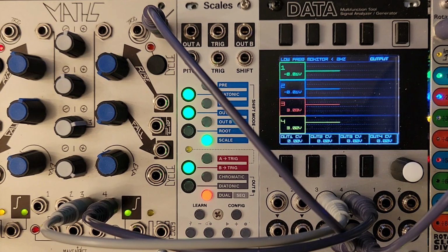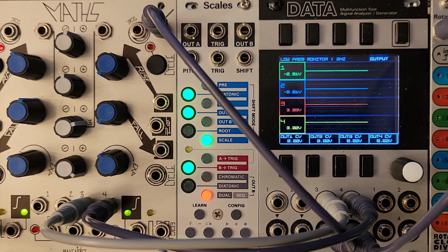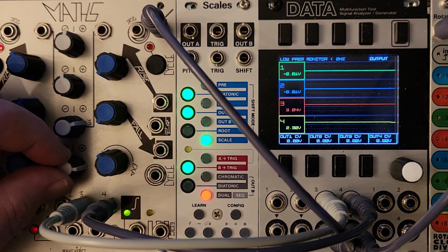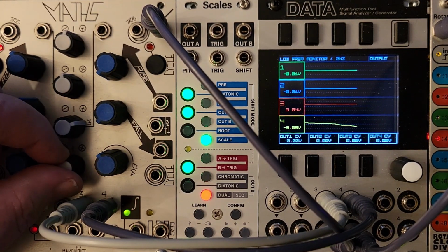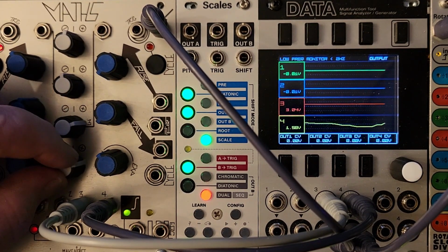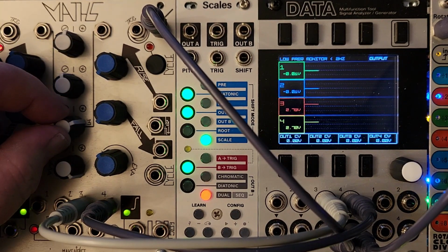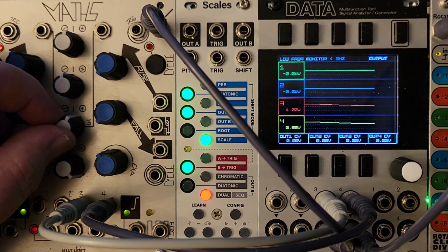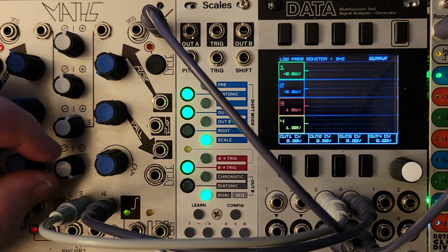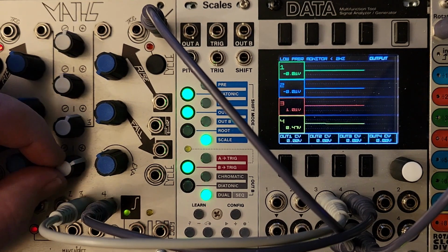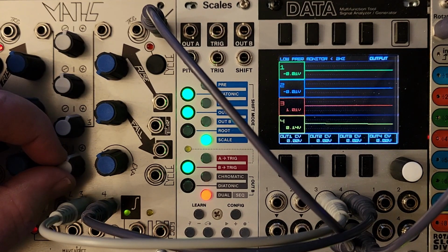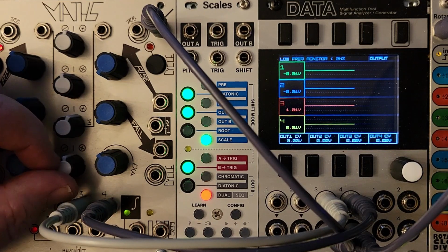In red is my channel 3 output, set to about 3 volts. Below that in yellow is the channel 4 output, and you can see that instead of going from -5 to +5, the channel 4 attenuverter now goes from about -3 to +3. Now I'm turning down channel 3, and you can see that channel 4 remains in lockstep with it. Channel 3 is the maximum value, so as it goes down, so does channel 4. So now I've got the range brought down to about -1 to +1 volts, and you can see that I'm getting very precise control. In fact, I can dial in 1/100th of a volt if I ever needed to do that.